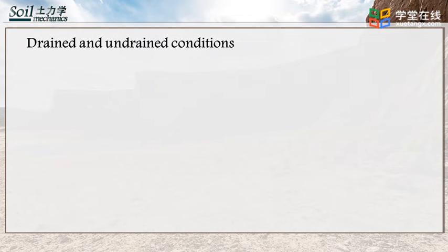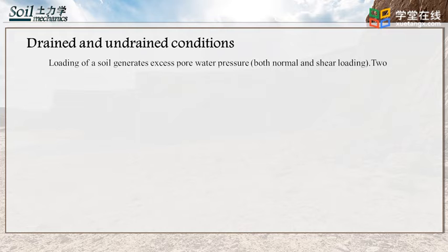In this lecture, we are going to learn some basic knowledge about one of the mostly used geotechnical tests, direct shear test. Before learning the details of the test, we need to be clear about the testing conditions. Loading of the soil generates excess pore water pressure. In tests, two extreme cases are generally considered, which are tests in drained and undrained conditions.